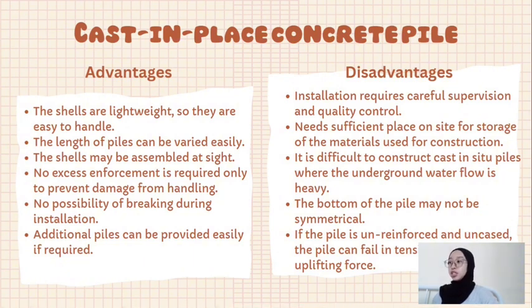Meanwhile, the disadvantages of cast in situ concrete piles are, firstly, installation requires careful supervision and quality control. It needs sufficient space on site for storage of the material used for construction. It is difficult to construct cast in situ piles where underground water flow is heavy. The bottom of the pile may not be symmetrical. And the last one, if the pile is unreinforced and uncased, the pile can fail in tension if an uplifting force acts on it.